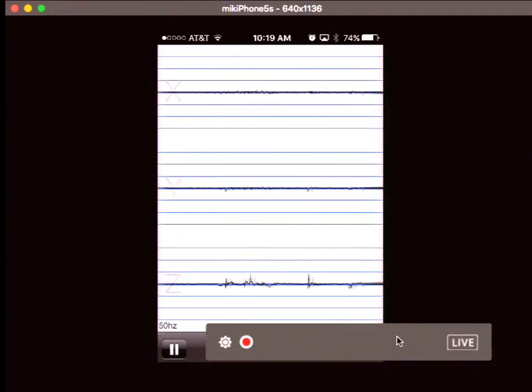What if I bang it so hard? What's going to happen to the accelerometer? Completely saturate, right? So it saturates, then it's nonlinear. If I hit again and again, the saturation makes it nonlinear. But if I make small hits in the same spot, then it's approximately linear time invariant.